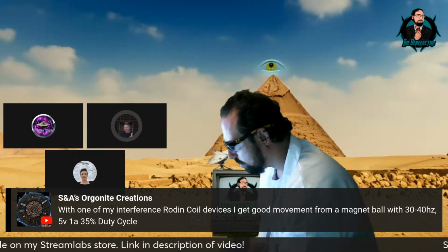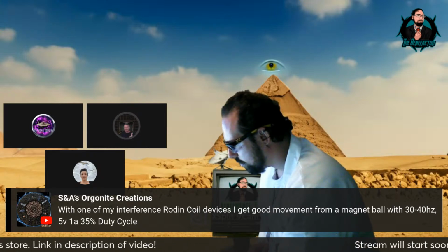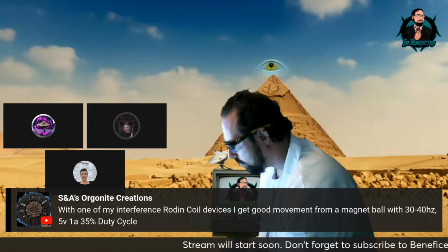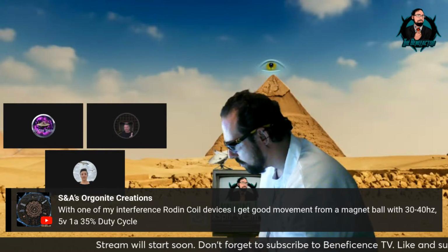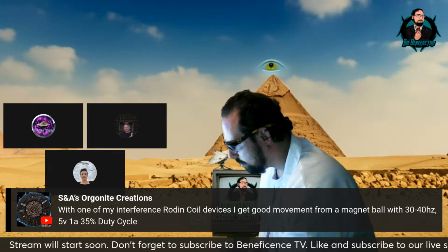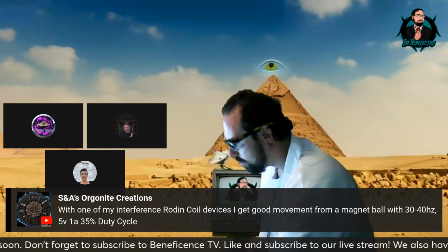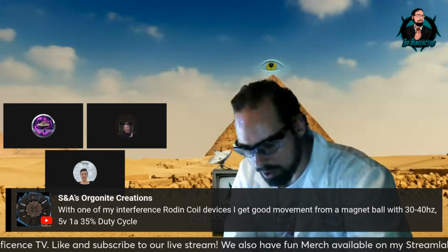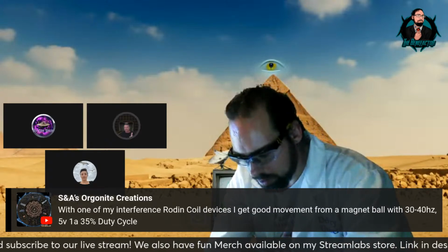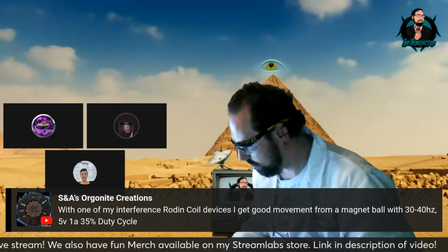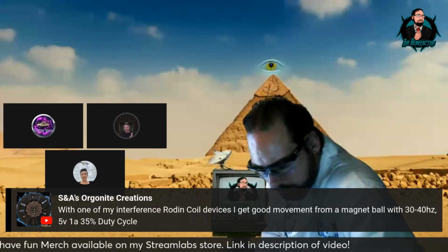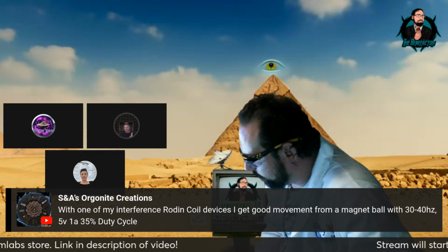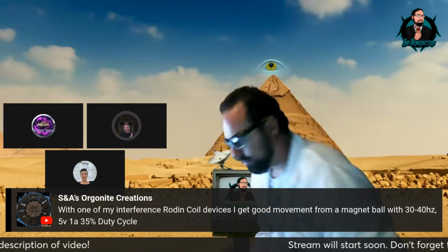See, with the stereo amp, he's able to put a signal in there at any frequency he wants from his laptop. So he can go to 7 hertz if he wants, but it's AC 7 hertz. Right, we're gonna test the code out in a minute. But he can also pulse DC through the signal generator into the stereo, and it would be the same thing as the PWM pulsing DC from the supply, because it's pulsing a DC tone.